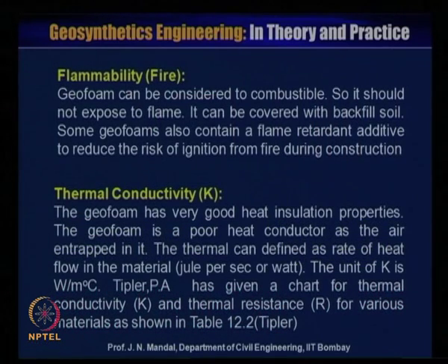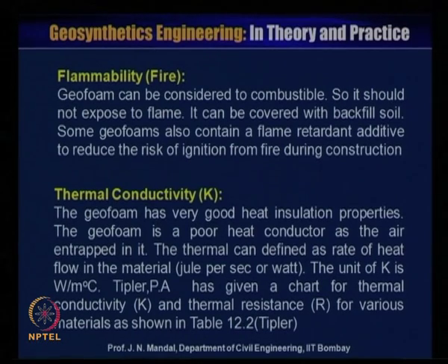Now, regarding flammability or fire, geofoam can be considered combustible. So, it should not be exposed to flame. It can be covered with backfill soil.